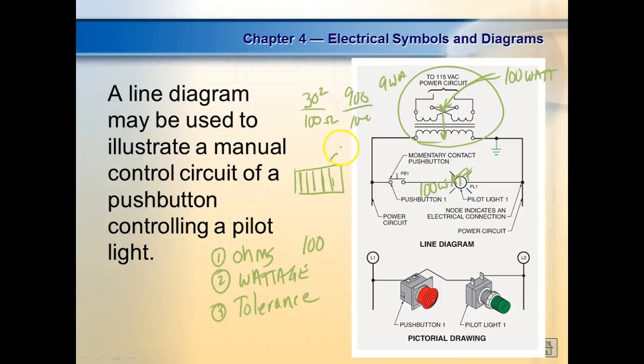These guys are going to have like a brown band on. What do y'all think brown would mean? 1%. Red would mean 2%. So we have 1% resistors we can buy. We got 2%. We got purple. We got different tolerances, but the stricter the tolerance is, the more it's going to cost, right? You understand? So normally here we teach 4-band resistors, but 5-band resistors are out there. I think they introduced those to you in the intro, right? 5-band resistors.